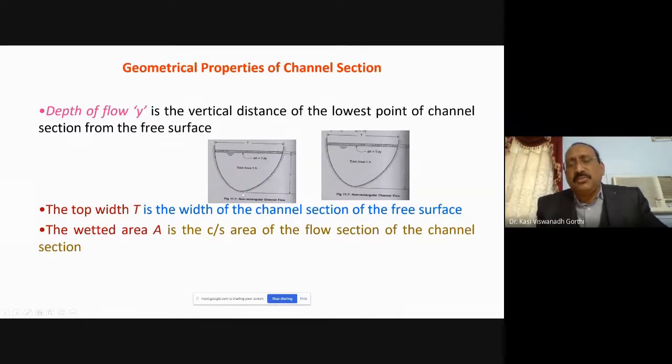If you leave this bottommost point, there are several other points at the bed. You may get different depths, but they are not considered to be the depths of flow. Depth of flow is only one at a given section. From the free surface to the bottommost point of the channel section is called the depth of flow Y. So depth of flow Y is the vertical distance of the lowest point of the channel section from the free surface. Next, top width T.